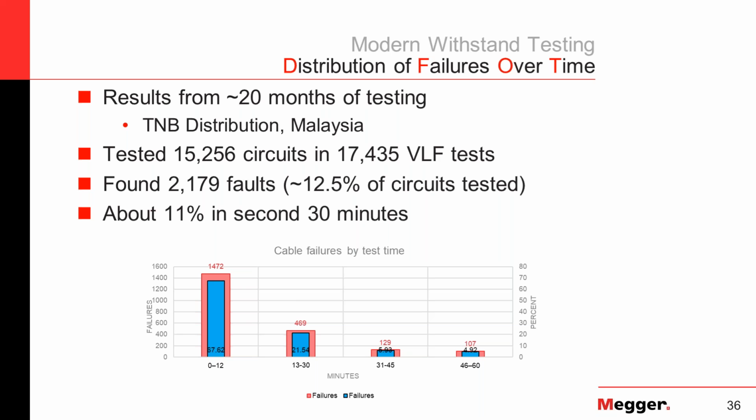And they had a certain failure rate. As you can see, in their system they applied the VLF test, and only 12.5% of the circuits failed initially. So this is not a destructive test. If only 1/8 of my population fails after I switched from a reactive to a proactive maintenance approach, from run to failure to actually doing something, that is a pretty good number.